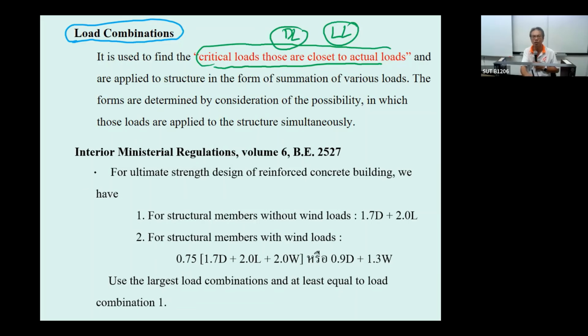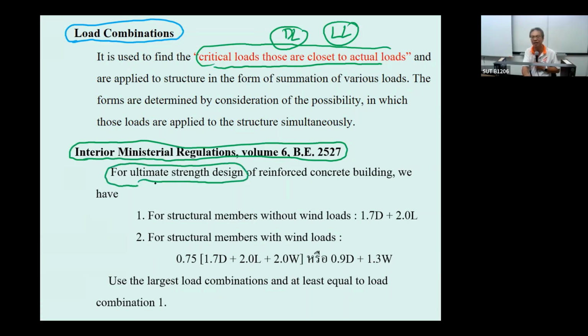So if you follow the Interior Ministry regulation, which is the legal document I just mentioned, and you design the structure based on ultimate strength design for the reinforced concrete building, the first step of the design is to use only this load combination.